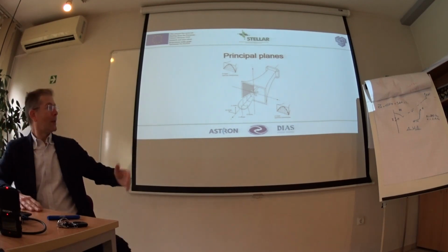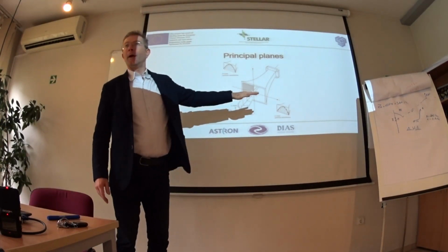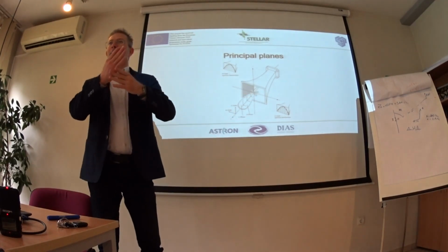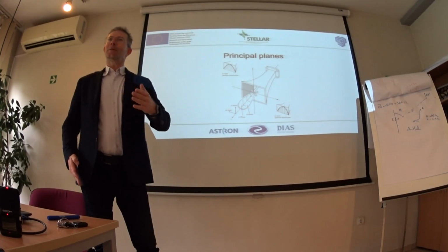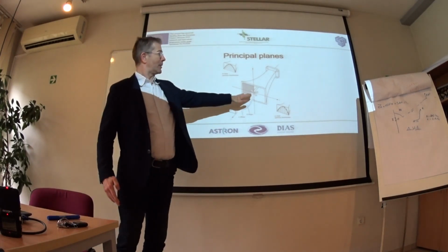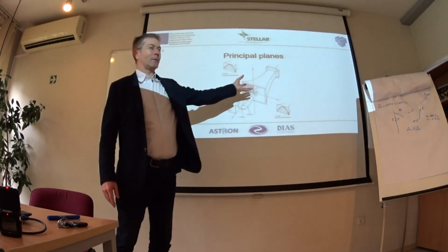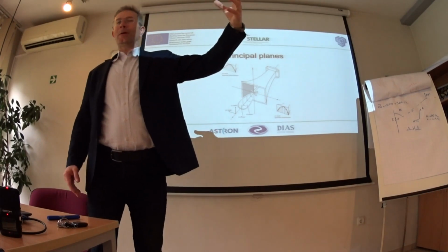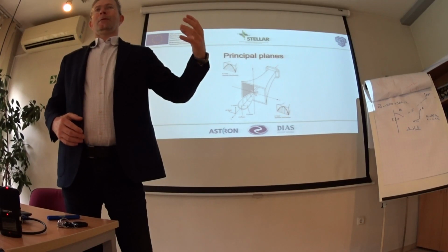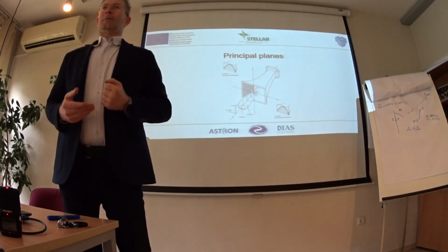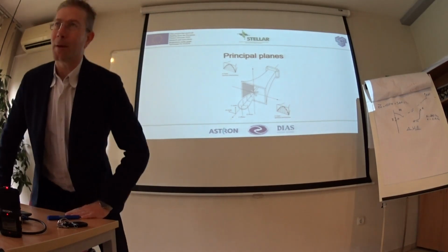And then we form a concept of E-plane and H-plane. One plane contains the E field, this is the E-plane, and oppositely, the other plane is the H-plane. And that's how, if we have this antenna placed on a spacecraft, we can tell the orientation of the antenna relative to the orientation of the pattern. So it's very easy when we are on the ground.